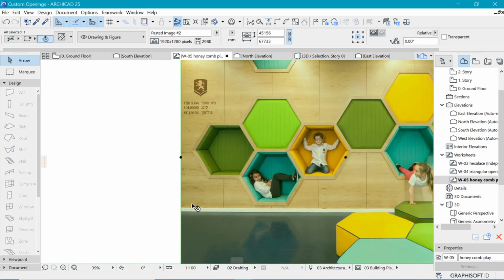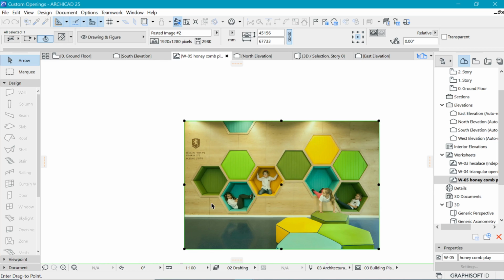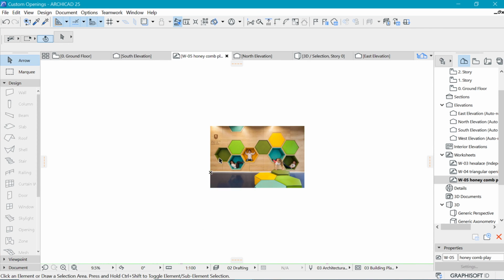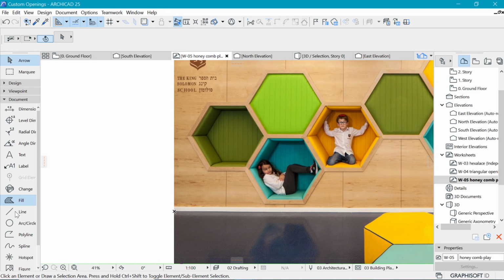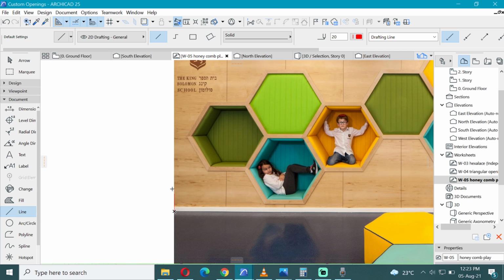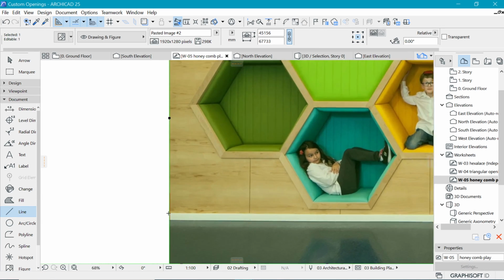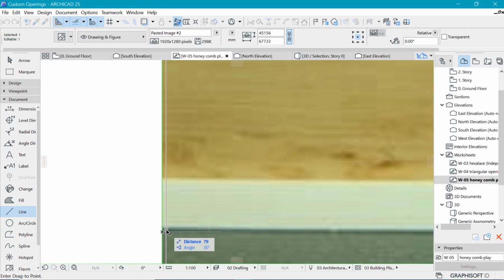For example, to get the scale right, I'm going to use the bottom here and put it at the X mark here, such that I can easily reference it. Pick a line here, which is going to be a different color, and I'm going to make this 3 meters, and this image is very huge, so I may want to scale it because 3 meters are already stopping somewhere here.